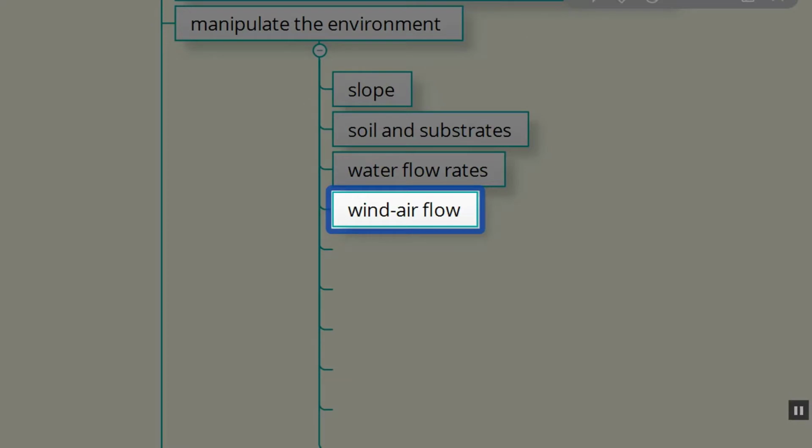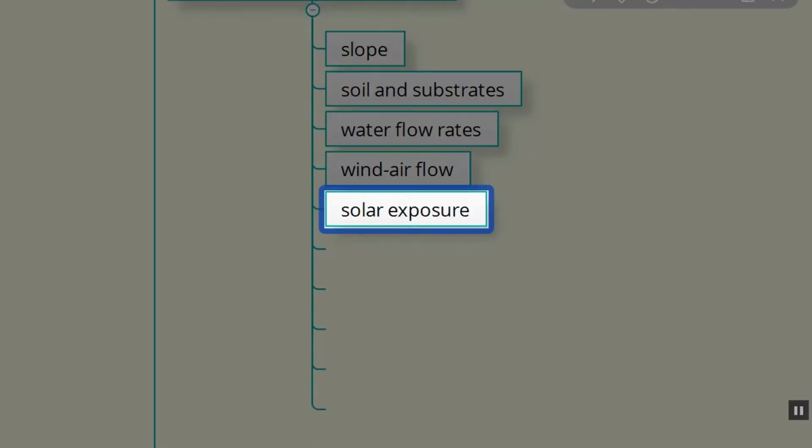What about the wind and airflow to the site, depending on what microorganism and which bioremediation system we're using? What about solar exposure? So fungi, breaking down the cardboard and paper products, you see I'm going into the woods because the fungi don't need the sunlight exposure. But the bioremediation systems that you've seen, the marginal zones around the ponds and canal systems I put in, they're in full sun exposure because those plants need the solar radiation in order for the plants to do their bioremediation.